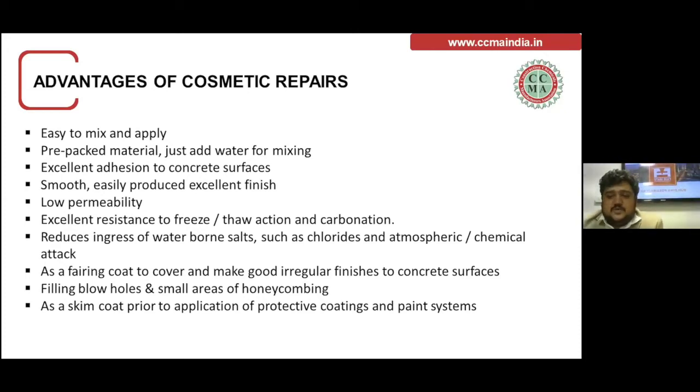It has very low permeability, so the water will not go inside, and thus will help in freeze and thaw and also carbonation. If the water does not go inside, the carbonation process will not happen. It reduces ingress of waterborne salts such as chlorides and atmospheric attack.